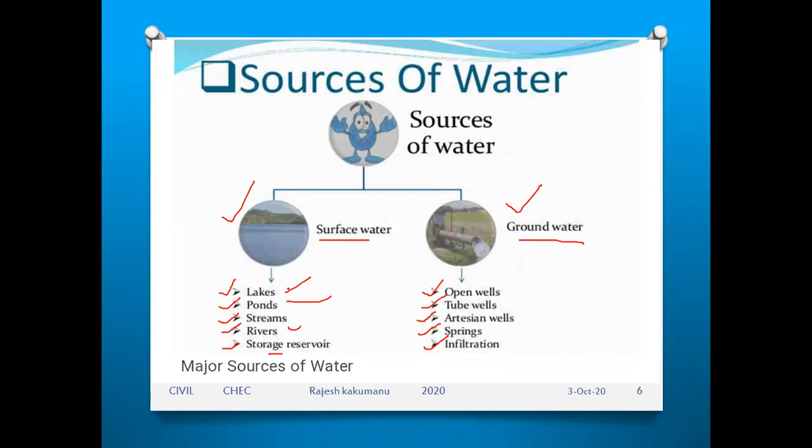There you are using the municipal water, thereby the water is converted into wastewater, that is sanitary sewage water. Then this water is coming through the pipelines and going to the wastewater treatment plant. In the wastewater treatment plant, again we are going for various treatment processes, that is primary, secondary and tertiary. There again you are testing the pH value of the water, physical properties, chemical properties and biological properties, and again you are retreating this water.